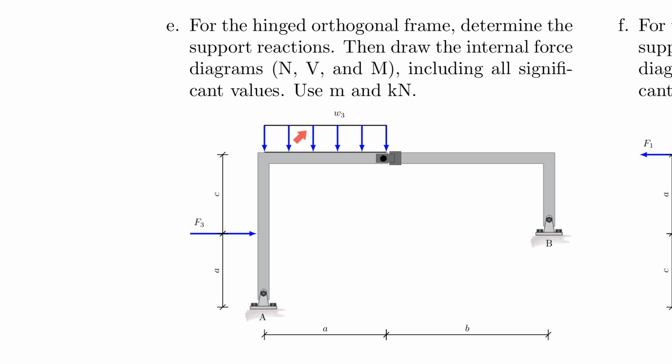In this case, the system only has load on it on the left side. This is to make your life easier so that you can quickly identify your 2 equations with 2 unknowns to find your first support reaction and then move on. And then everything you learned from before in the homework applies as well. Once you found the support reactions, it is really not different. So of course you need a reference fiber again, because that really determines how your diagrams are drawn in terms of positive and negative regions. So that completes this problem.